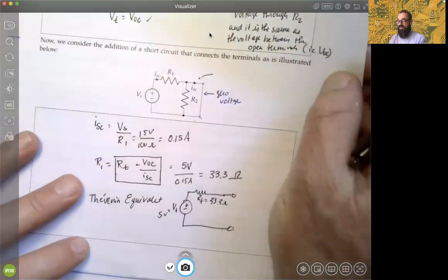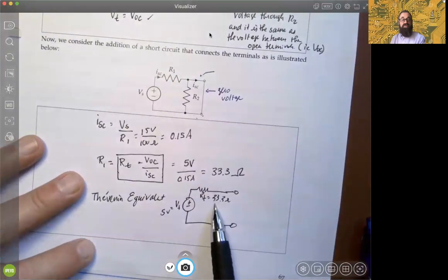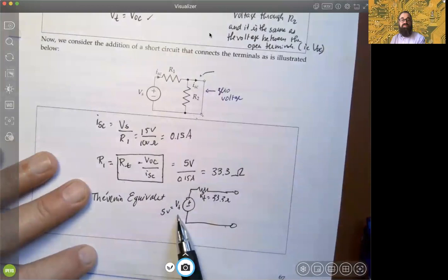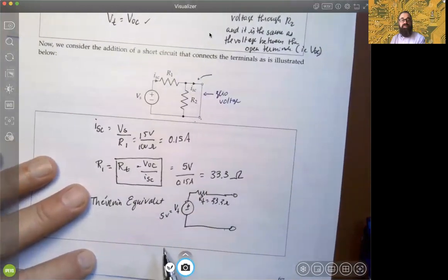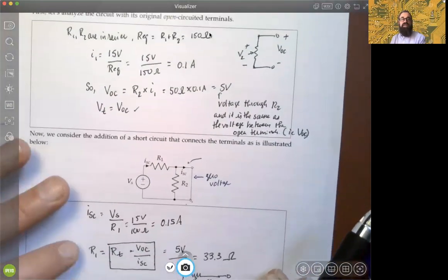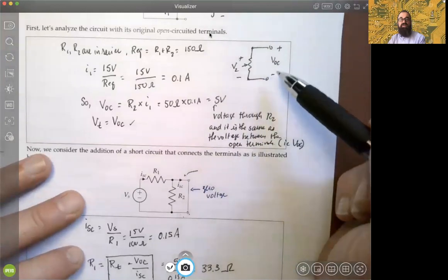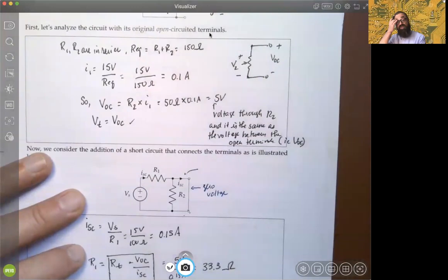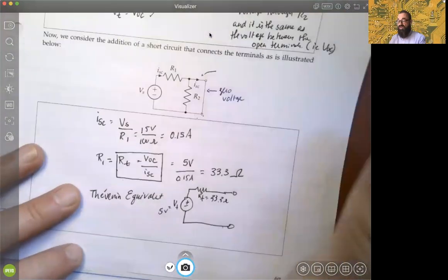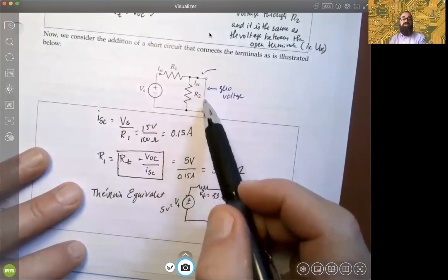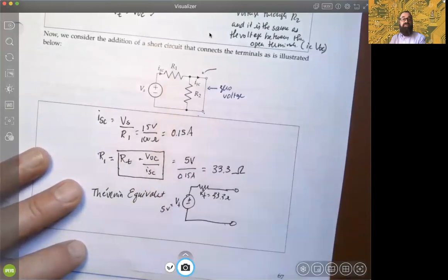So this is absorbing and represents all the load that you would get and essentially how much voltage will be delivered, okay? Right? Okay, so that's one example of a kind of brute force technique. You analyze what you can across the open circuit for the voltage of the open circuit, then add the short circuit, and then try to use the fact that you can determine perhaps the resistance directly.